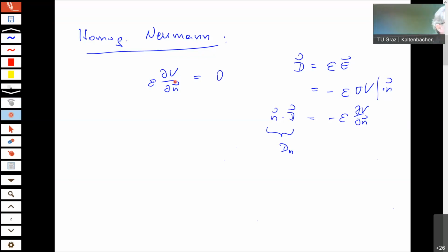Okay. So as you see, standard is that this is 0, meaning that the flux lines we have there, our field lines, will be along the tangential plane of our computational domain. They don't go out of the domain. Yeah? But very good, we could also have there some surface charge. Yeah? And that is if you have a charged electrode. Yeah?